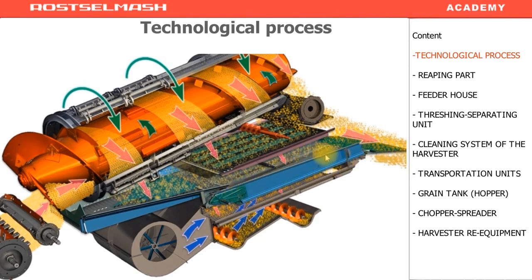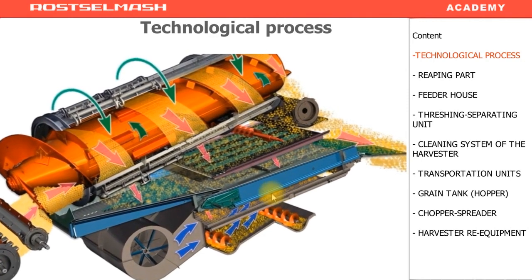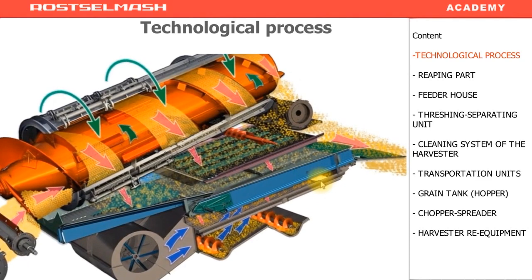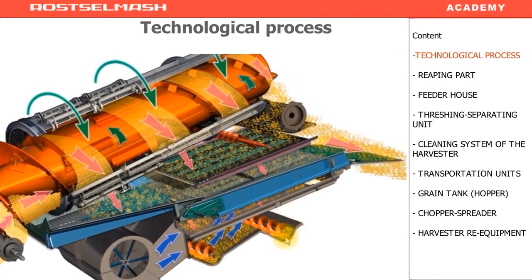From the upper sieve, the clean grain falls on the lower sieve. Some unthreshed wheathead fragments may fall on it as well. The clean grain is spilled and transported to the grain auger. If a wheathead fragment gets in there, it can't go through the lower sieve. It is moved to the end of the sieve, and then, down the chute board, it falls onto the tailings auger.